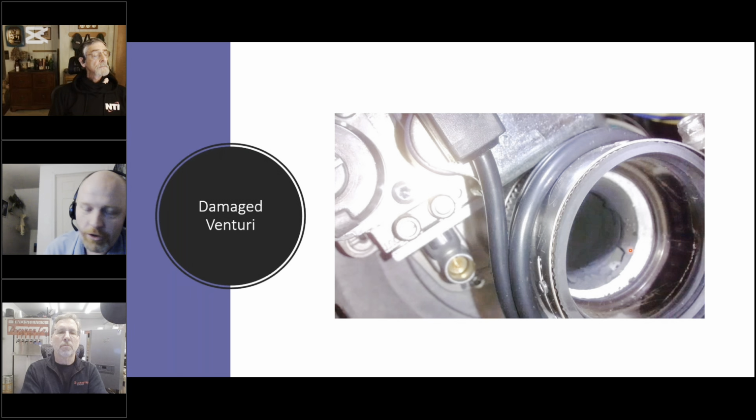And so of course this boiler just could no longer be set. I think it was on propane and we could get 8% CO2. That was the best we could hope for. Put a new venturi on it, and of course it worked great.